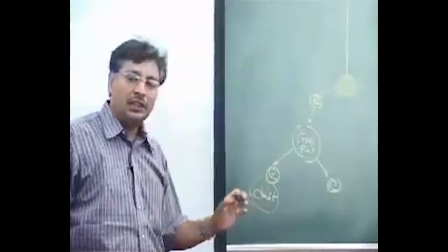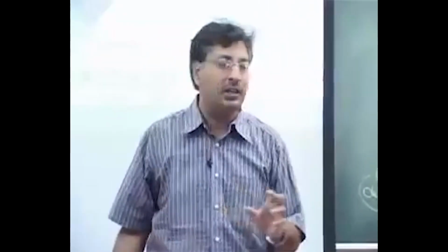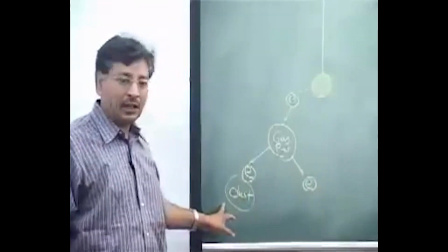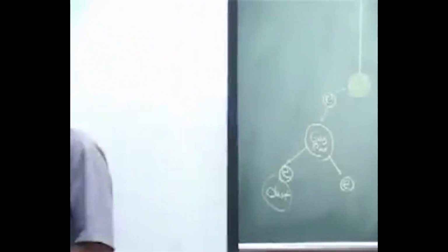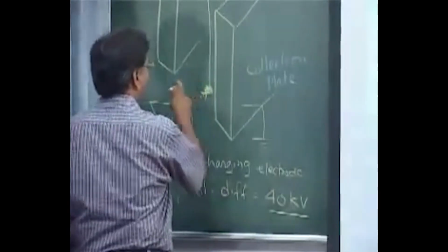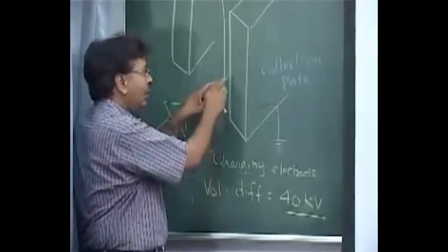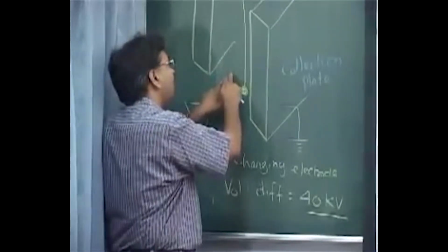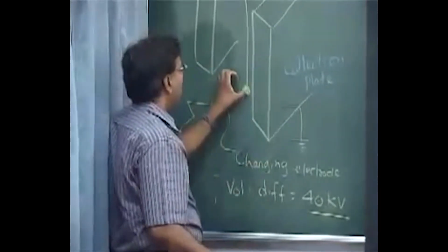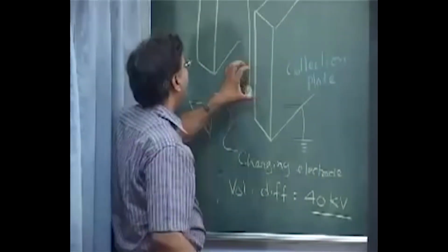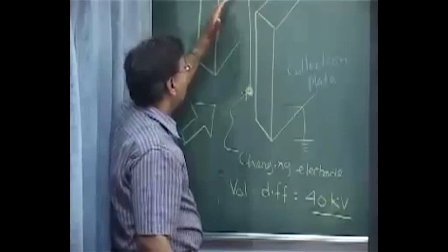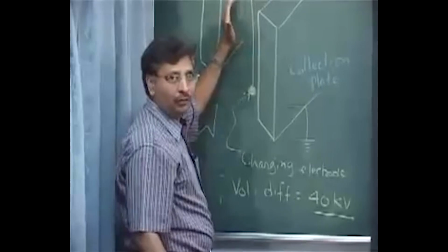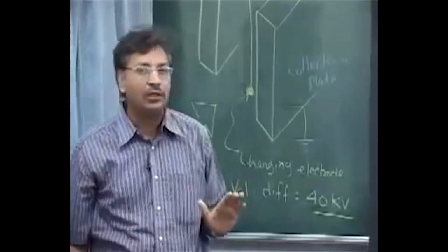Okay, this dust particle will also start traveling in the direction opposite to the discharge electrode and go towards the plate, because they were going towards the plate anyway. The electrons have to go towards the plate, but on the way more electrons become available, and they sit onto the particles, and then the drive continues towards the plate. So as a result, all the particles start moving from wherever they are back to the plates. The moment they hit the plate, they will discharge and stick to the wall. So this is the mechanism, this is how this happens.